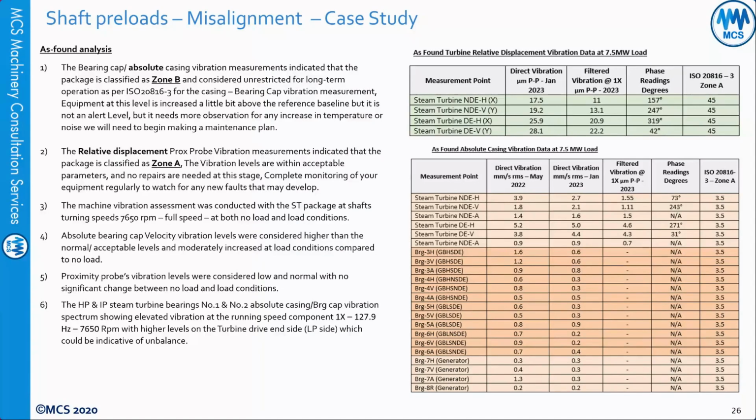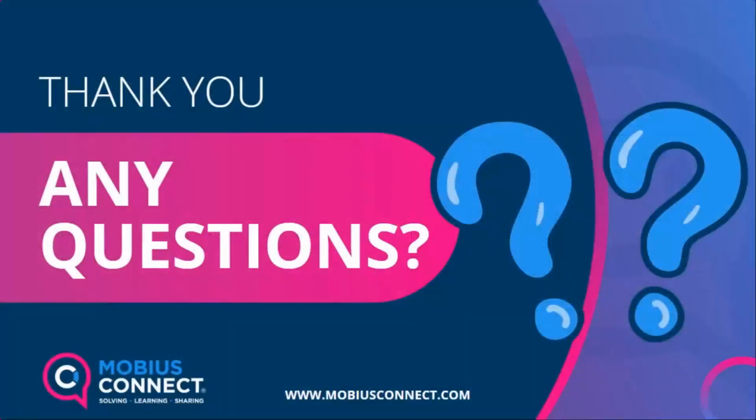The most important thing was for the two proximity probes to be 90 degrees apart. In some situations they can be more, depending on the bearing design. But in this situation we only had this chance, because holes were already drilled in the bearing caps, and this is what we used to install the proximity probes.